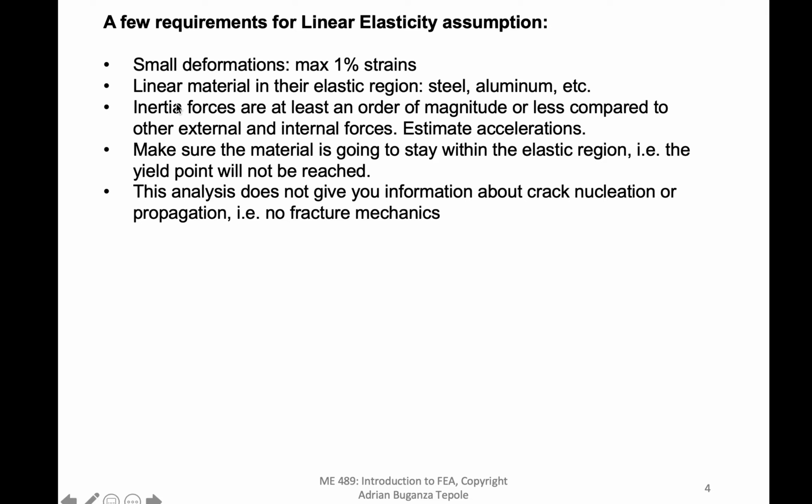Then another one is that in the linear elasticity problem, we are not solving for the accelerations or velocities, so this is a static problem. Therefore, make sure that the inertia forces are at least an order of magnitude smaller compared to the internal forces, compared to the stresses. And for that, what you need to do is to estimate the accelerations in order to know whether or not the inertial forces are going to be significant.